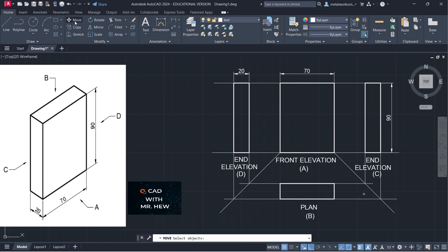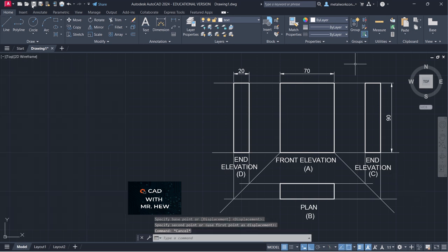So we're going to go to the move command under the modify ribbon. Going to click on the C with the brackets, press enter. Those are the objects that I wanted. I'm going to move this and put it right here so that it looks neat. Enter. Also, we're going to select the A with the brackets and we're going to try and center it so that it looks neat. Enter. That's much better. All right, I'm going to press save.